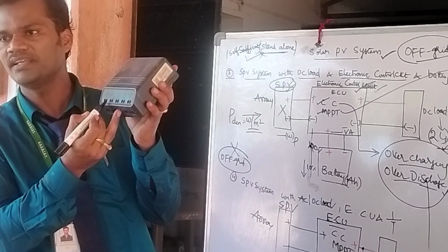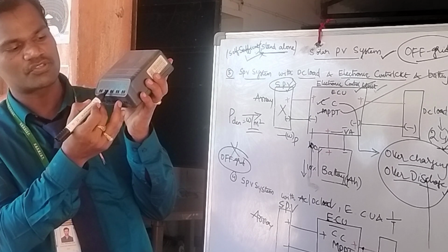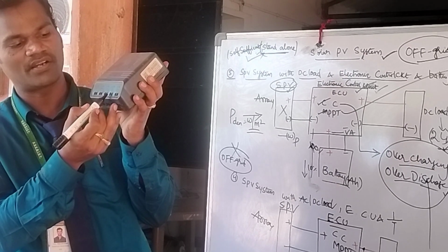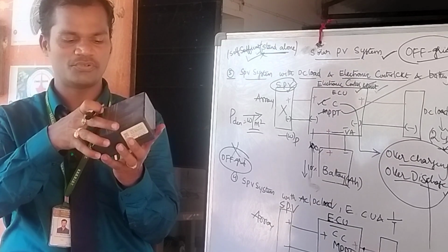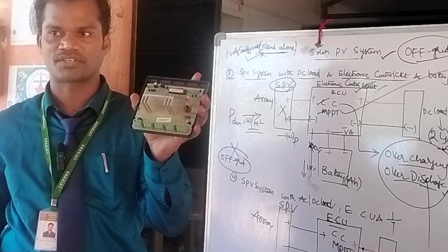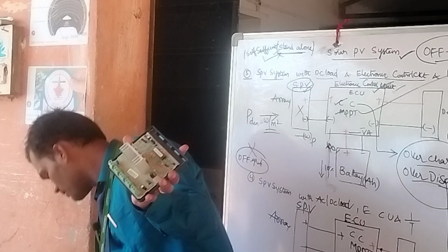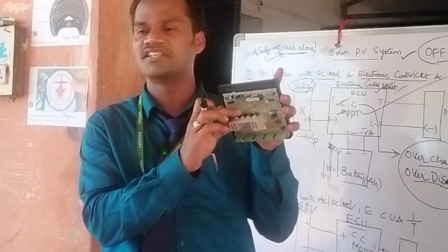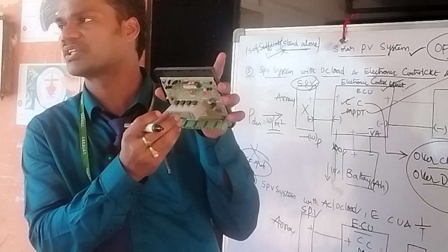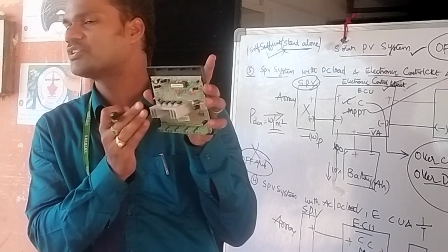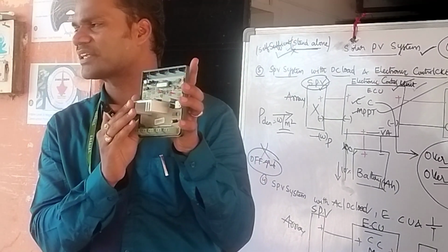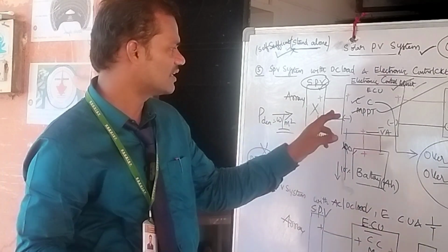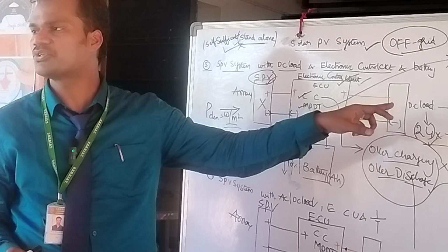Okay. So this is generally how it works. When put in a circuit, you can run the circuit. As I told, we are going to extract the maximum voltage and current. We have a number of algorithms. All those algorithms are implemented in the microcontroller. And the solar power is given. Automatically it tries to capture that maximum voltage and current, and it will try to put maximum power in the battery. If the battery is full, automatically it will try to discharge. We have an implementation part. On this, we'll try to do that experimentation.